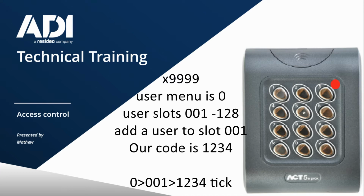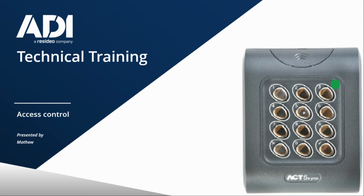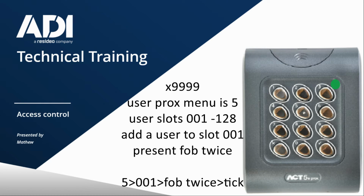Now I'm going to put a code in for user 1, a 4-digit code. You heard the reassurance tone, and the LED is now flashing orange. Press tick. LED is flashing red, and then press X, and there we go. User 1's programmed in. And just to confirm, you'll hear a different tone when I put the code in. So you hear the double tone, the dual tone, the LED's gone green, and the relay changed state. So that's user 1 programmed in with a pin.